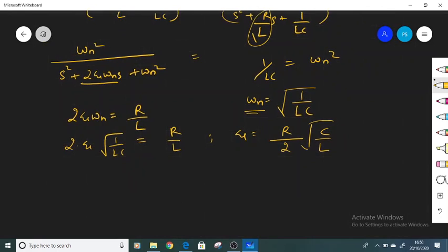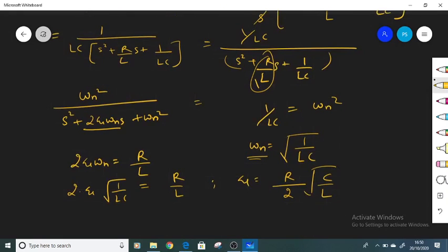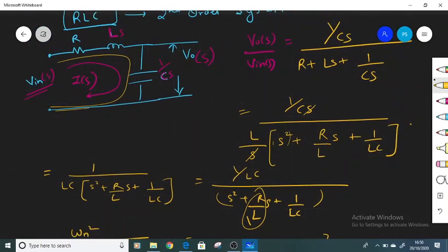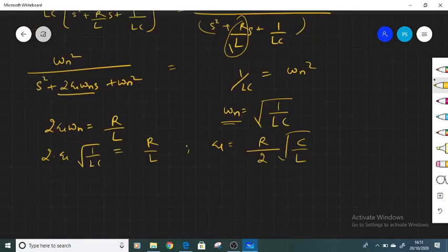Okay. Now when you have this system, जैसे आपके पास ये सिस्टम है, आपको ये सिस्टम डिज़ाइन करना था. सपोज ये कहा गया था टास्क वाज टू डिज़ाइन एन RLC सिस्टम. ओके, आपने RLC सिस्टम डिज़ाइन कर लिया. Now based on the values, here you can see that based on these values, R की क्या वैल्यू होगी, C की क्या वैल्यू होगी, L की क्या वैल्यू होगी. Based on these values you can vary the zeta. और omega n की क्या वैल्यू है? Omega n is 1 divided by root LC.